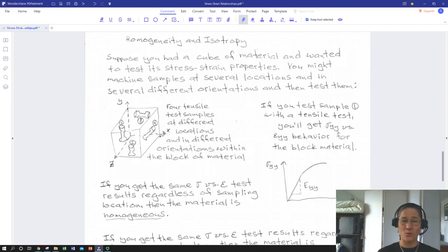And for isotropic materials, we'll be able to describe all of the elastic properties with like 3 values that are related themselves. For non-isotropic materials, we need an entire matrix because, for instance, elastic modulus could be different in the X direction, Y direction, Z direction. All the other elastic constants could be different in all the different directions.